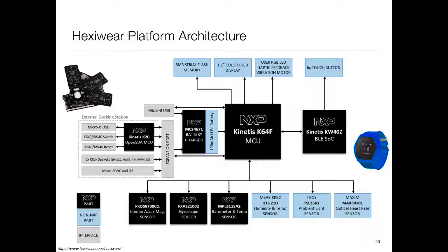From a platform perspective, what we have in something like this is a main MCU. This is the Bluetooth one with the BLE SoC. It talks using a serial link. There are a whole bunch of sensors attached to it. This is what is called an inertial measurement unit: an accelerometer, a magnetometer and a gyro. The accelerometer, for those who don't know, measures acceleration in X, Y, Z.